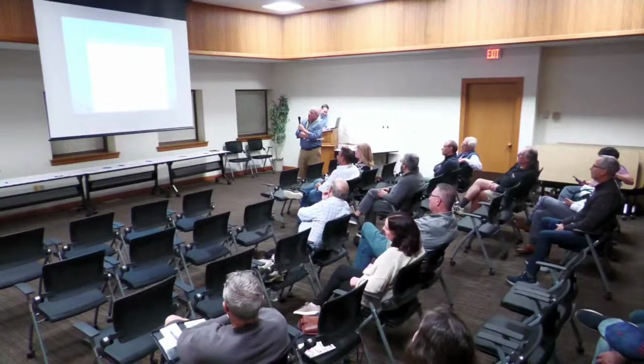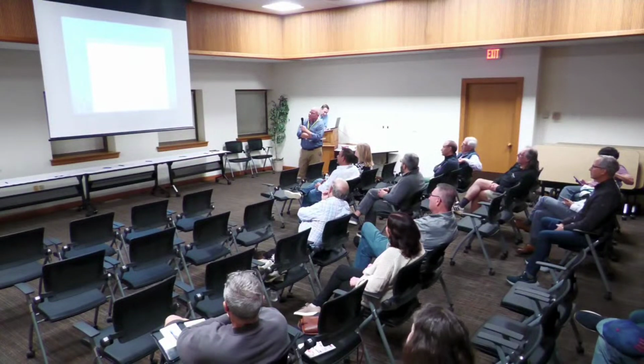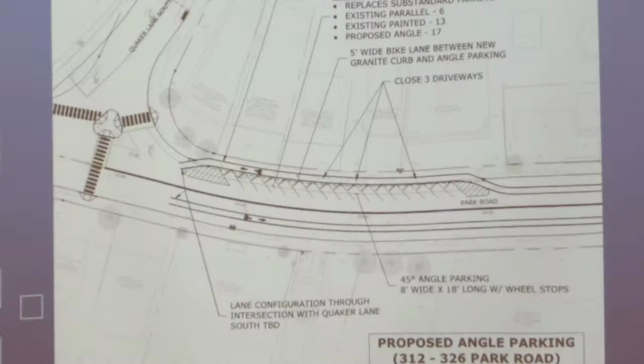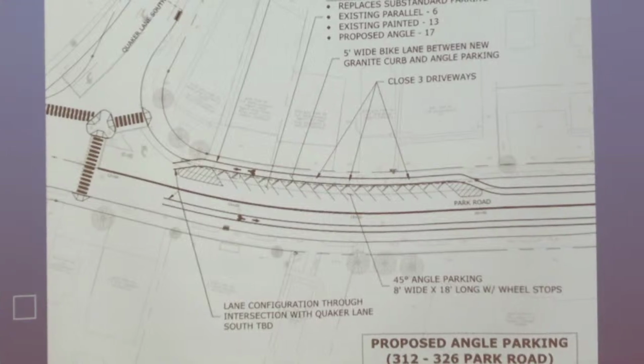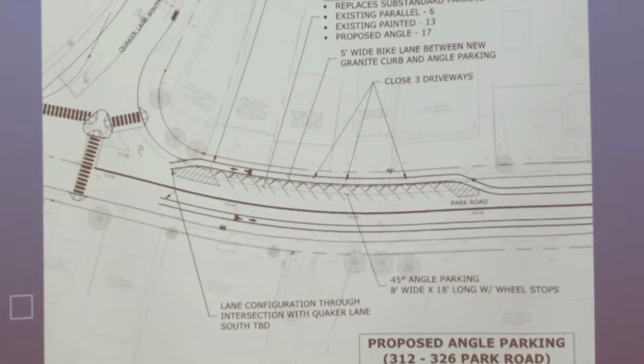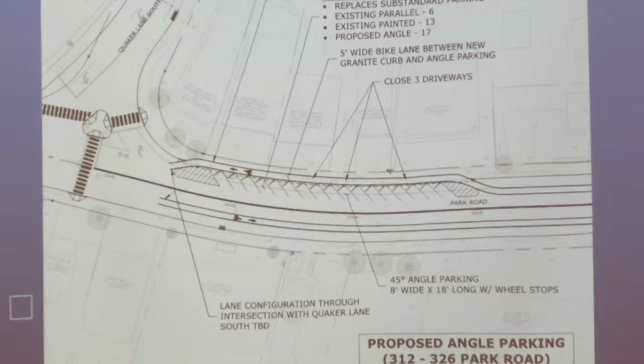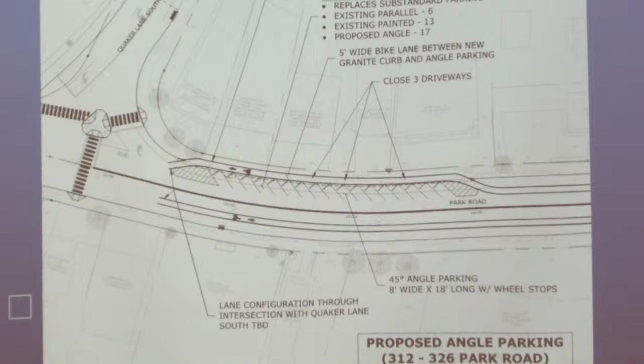Yeah. Right now, the driveway aprons have striping that's been put down on the private property side in front of the buildings to support parking. But none of the driveway aprons really line up with that. And the problem is that if cars could get in, somebody could parallel park behind them, and then you can't back out. They're having to back over the sidewalk, drive on the sidewalk to get into the stall.